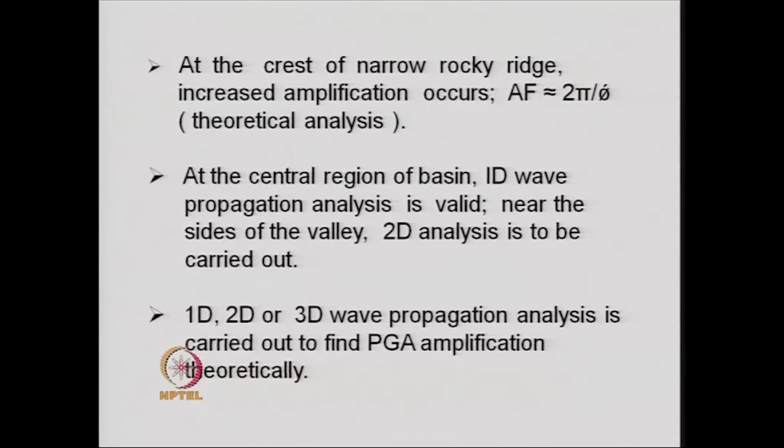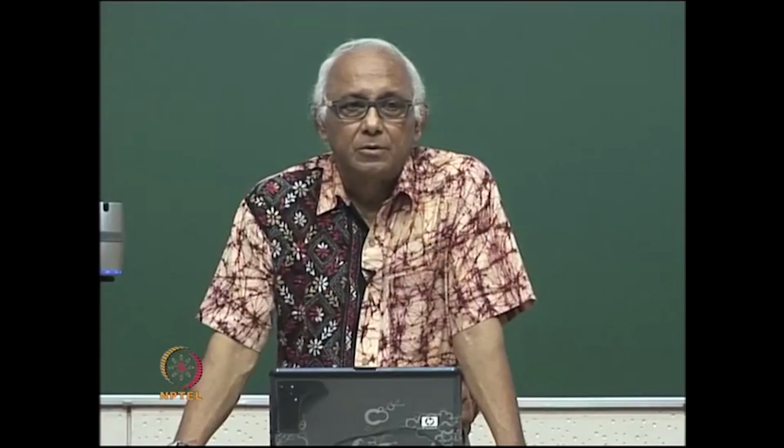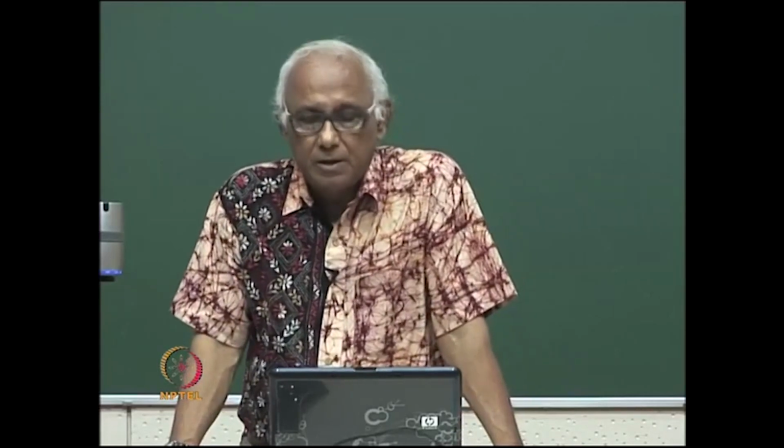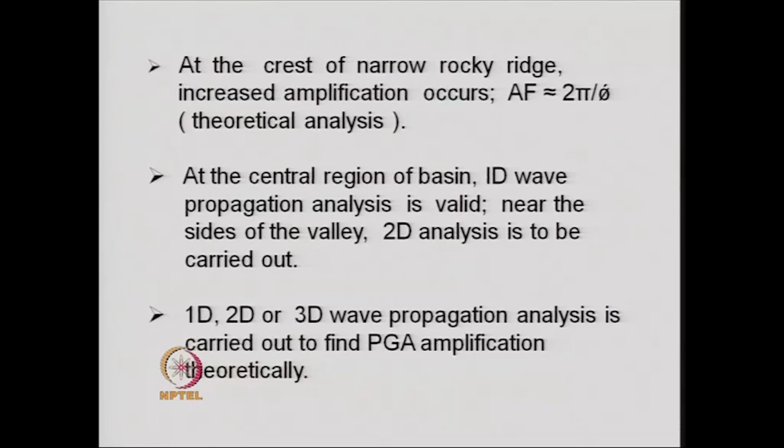The ground amplifications that were observed from the collected data were later on verified by the wave propagation analysis, and the analysis showed that the observations made from the different records are quite valid, in the sense that the seismic wave propagation analysis gives more or less the expected amplification factors.